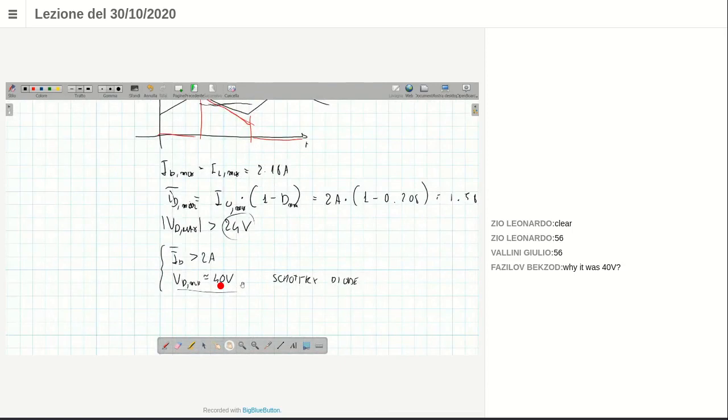Well, I have told that there are no normalized values for diodes, but it is the value of a rather low voltage diode to take a safety margin. Let me say we should take at least 20% safety margin. We would get something like 30 volts.